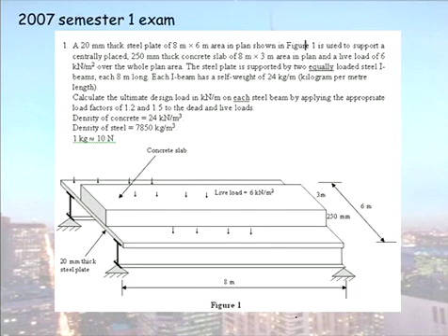And you're given the weight of the I-beams. So they weigh 24 kilograms per metre. Question very simply, calculate the ultimate limit state design load on each steel beam by applying the appropriate factors of 1.2, 1.5. This is quite an old question. Not sure we always tell you what the appropriate load factors are. We would say calculate the ultimate limit state load and assume you know the load factors are 1.2, 1.5.